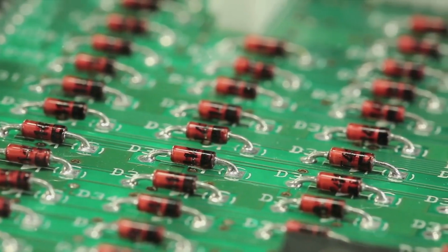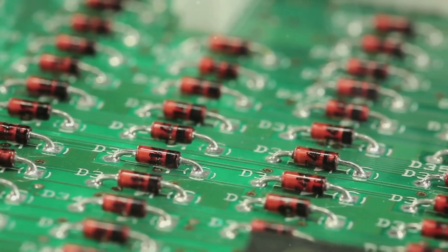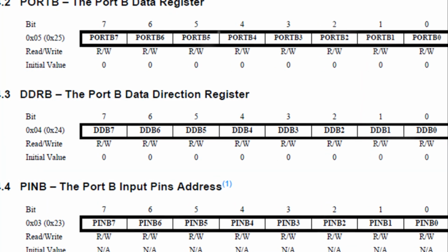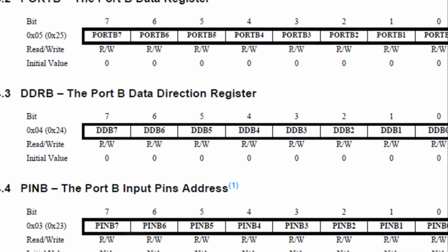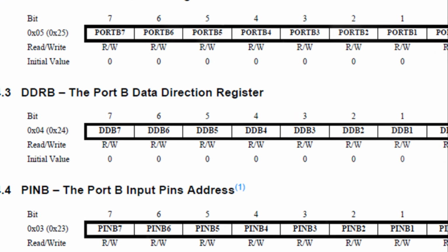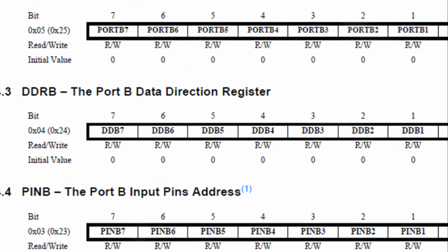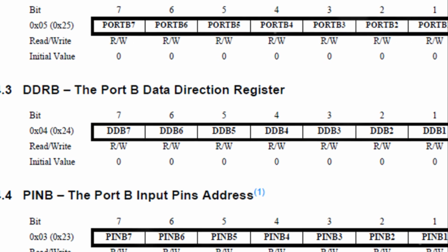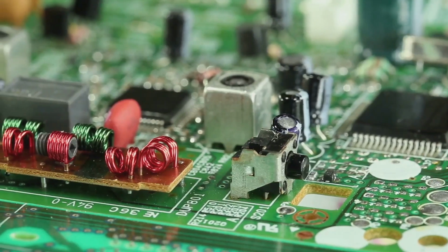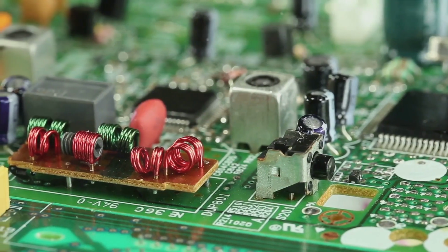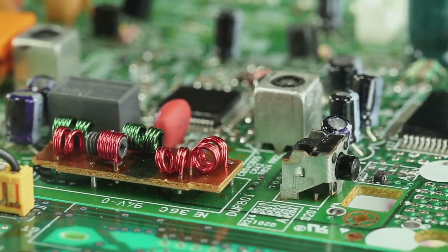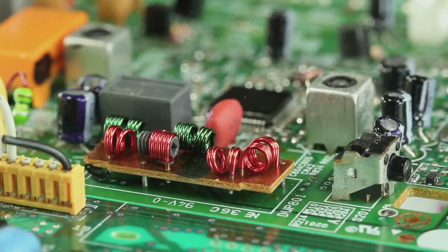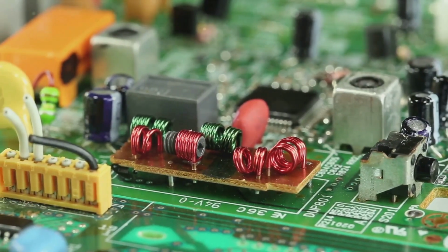Registers are basically just named memory locations that typically control I/O operations in a microcontroller. Ports are just a collection of registers that apply to one specific peripheral, such as GPIOs or ADCs. For this introduction to register programming, we will only cover 2 registers from port B, DDRB and PORTB. DDRB is the data direction register and controls whether a GPIO pin is an output or an input. The lower 4 bits correspond to the 4 GPIO pins B0 through B3.